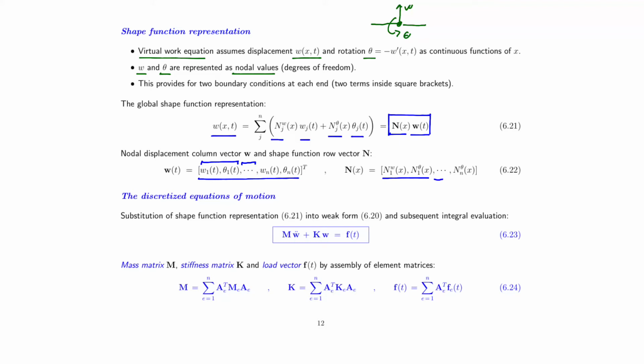And if we substitute that into the weak form formulation, we will end up with the classical finite element equation, similar to that we got for the cable. To demonstrate this, let's have a look at the virtual work integral for the stiffness matrix. We just need to get that right. Like this. Then we substitute in the expression for w tilde.